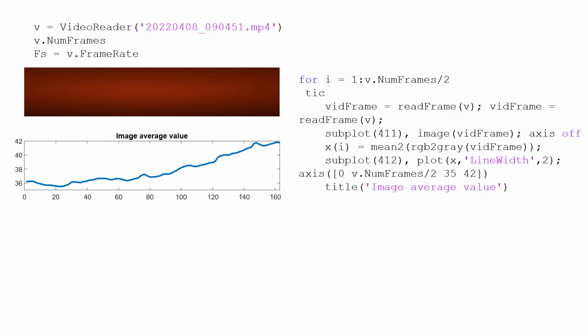And as we have seen before, that's the average values of all the frames available, which is a little bit more than 160. So that's my signal x of n. In order to do the processing, I know that my filter requires those 2 samples, so I will have to wait a little bit before I process an output because I need the current input, x of n, and I need to discard the following input and then wait for the next one and do that subtraction.